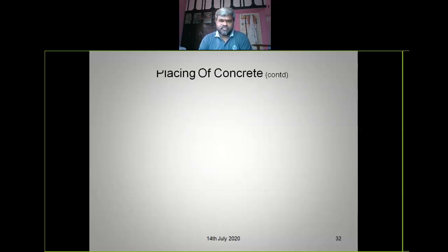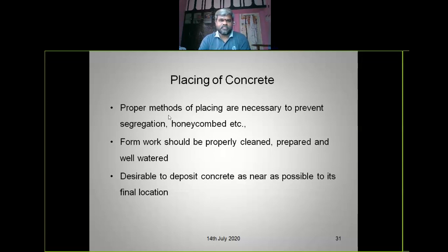And next, placing of concrete. This is transportation. Next, placing. Proper methods of placing are necessary to prevent segregation and honeycombing. Formwork should be properly cleaned and prepared and well watered.